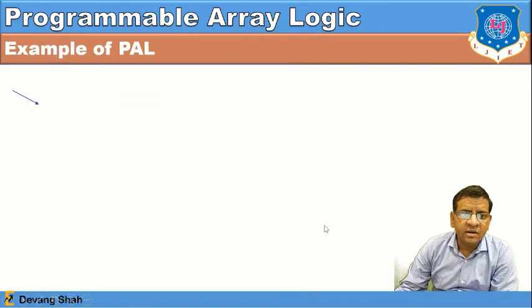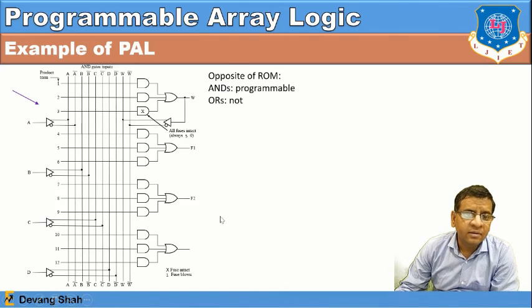See the next slide, and you can see the design where the implementation of w is already made, and the complement of w I'm going to use for the rest of the boolean functions I want to get, like f1 and f2, right? Once you implement this term as w and w bar, you can see this is a part of the programmable AND arrays, or part of the programmable input lines, and based on that you can implement f1 and f2 and more functionality, right?